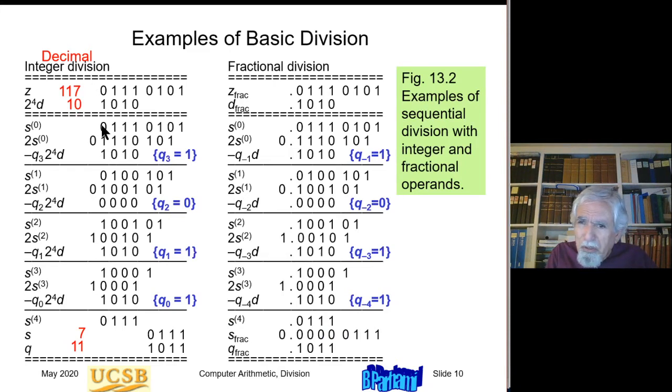You see, initially the partial remainder is 8 bits wide. Then it becomes 7 bits wide after we have selected, so that quotient bit goes there in that empty space. Okay, then it becomes 6 bits wide here, 2 empty slots, which will contain 1 0, the quotient. Then it becomes 5 bits wide, and the 3 slots here will contain 101. And finally, it becomes 4 bits wide, and the quotient is now sitting here. The quotient, which is 1011. So the two registers can be shared.